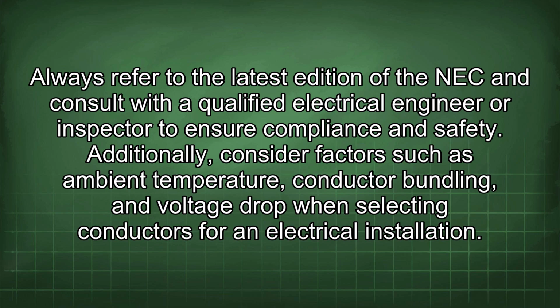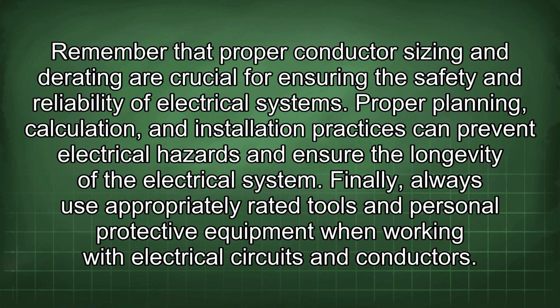Always refer to the latest edition of the NEC and consult with a qualified electrical engineer or inspector to ensure compliance and safety. Additionally, consider factors such as ambient temperature, conductor bundling, and voltage drop when selecting conductors for an electrical installation. Remember that proper conductor sizing and derating are crucial for ensuring the safety and reliability of electrical systems.